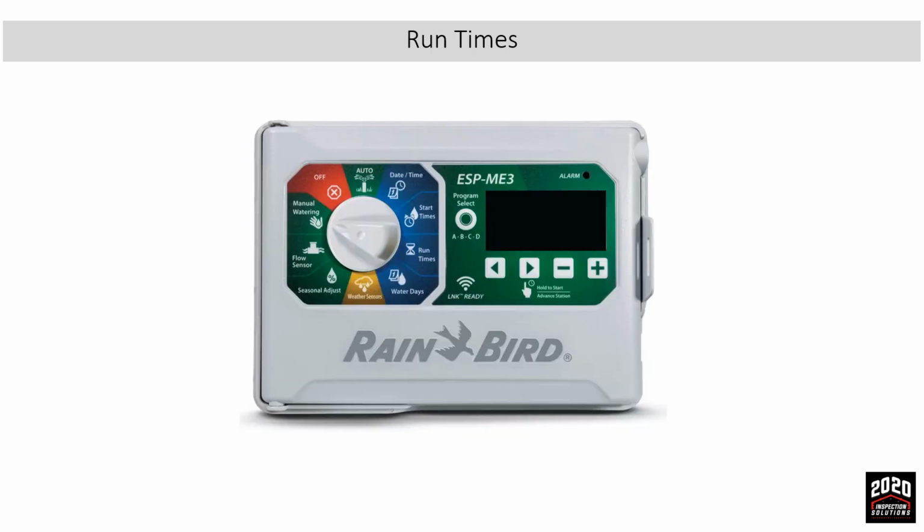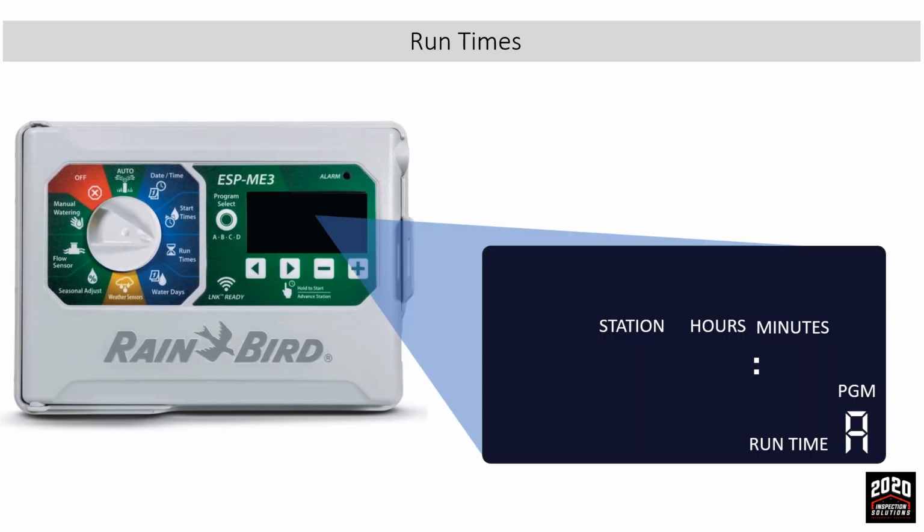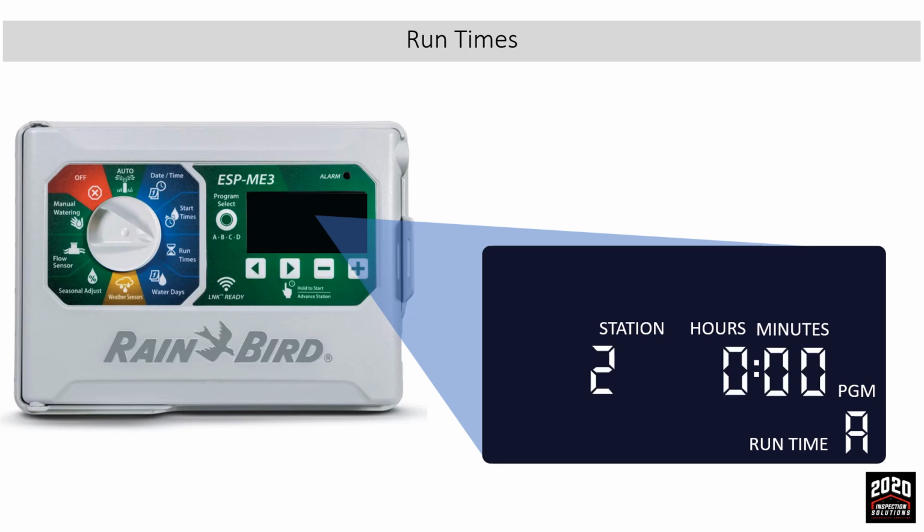Setting run times. To set run times, turn the dial to the run times position. Here is where we designate the length of time that each station within the program will run for. Let's program 5 minutes on each of the 2 stations. Do this by pressing the plus or minus button to 5 minutes. Then advance with the right arrow to station 2 and repeat the process, putting in 5 minutes. We'll leave the rest of the stations set to 0. Run times are now set.